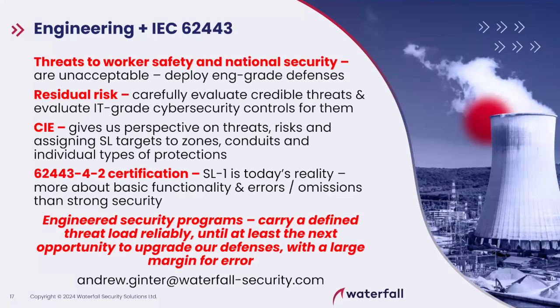So, if the safety system is your last line of defense because you don't have an electromechanical safety, it has to work. It must be protected. You need network engineering. The most common network engineering I see on safety systems is not unidirectional gateways, it's analog signaling. You want to monitor the safety system from the HMI, run a handful of 4 to 20 milliamp loops out of the safety system into a PLC connected to the HMI. And now you can see what's going on in the safety systems, but you cannot send any messages into those systems that would attack the systems.